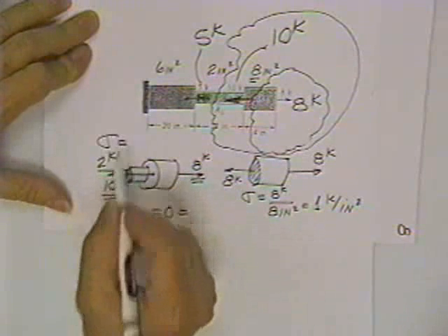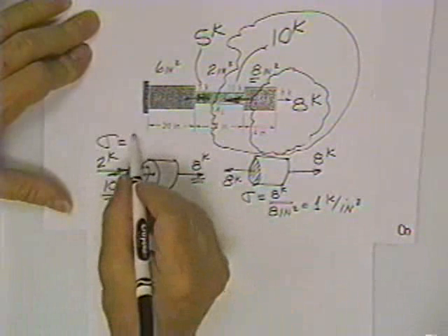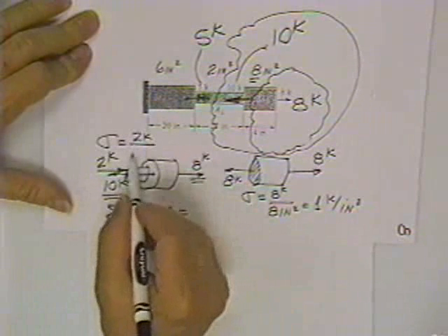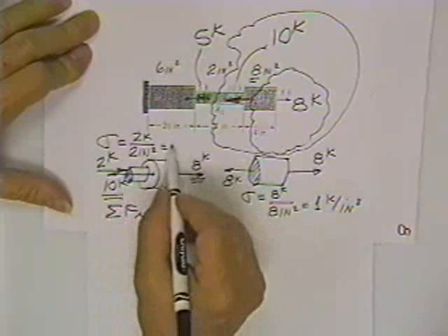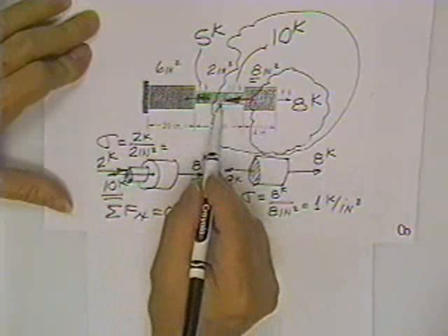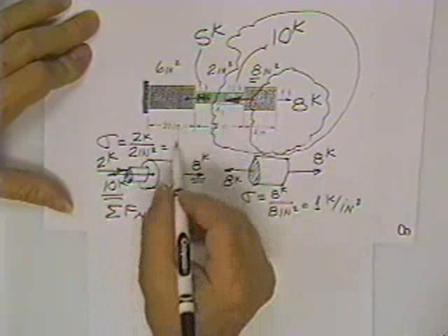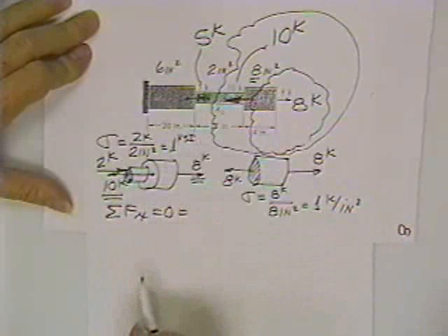It says that the stress in that section of the bar is the load, 2 kips of load divided by, how convenient, 2 square inches. Turns out the stress in the small piece is the same magnitude as the stress in the large piece, 1 kip per square inch.